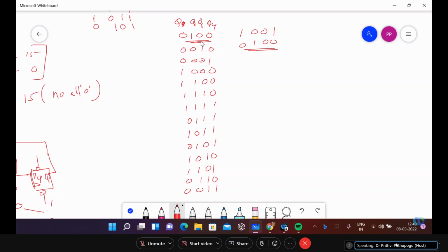Whatever initial combination you assume, with the feedback of 1 and 4 that we are giving now, that 1 and 4 is not able to define the all-0 combination. Based on the initial pattern, or initial value you are defining, you need to introduce the feedback from the complement bit so that it will make the output go to all zeros.